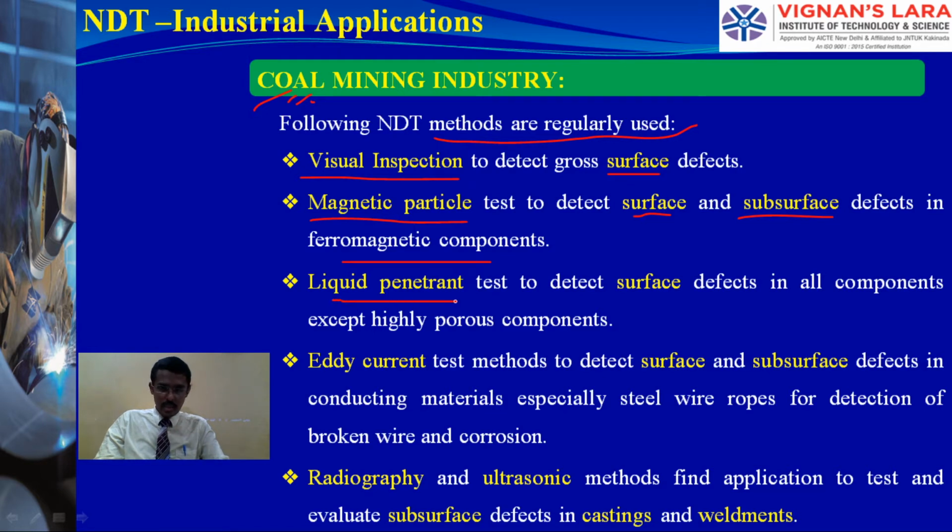Liquid penetrant testing detects surface defects, eddy current testing detects surface and subsurface defects, and lastly radiography and ultrasonic find, importantly, the subsurface defects in castings and weldments. We repeatedly see that our NDT techniques are much more related to welding and casting.